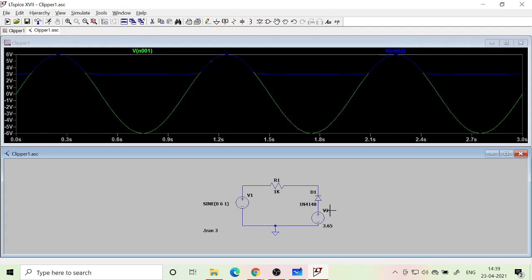You just need to look at the P side voltage, and any voltage lesser by a cut-in voltage than the P side voltage on the N side will make the diode forward biased. When it is forward biased, you get 3 volt at the output. So here it is minus plus, and the drop across the diode is plus minus. Okay, so that's what we need.